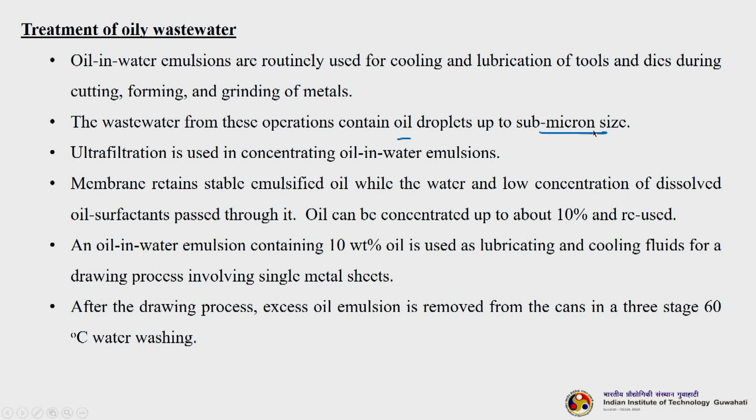Now, ultrafiltration is used to concentrate the oil water emulsions. Membrane retains the stable emulsified oil, while the water and low concentration of dissolved oil surfactants pass through it. Oil can be concentrated up to about 10% and then it is reused. Now, an oil in water emulsion containing 10 wt% oil is used as lubricating and cooling fluid for a drawing process involving large metal sheets.